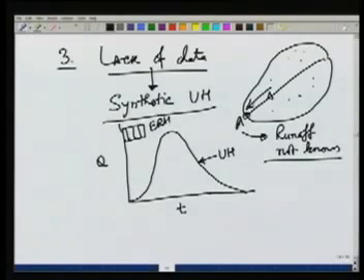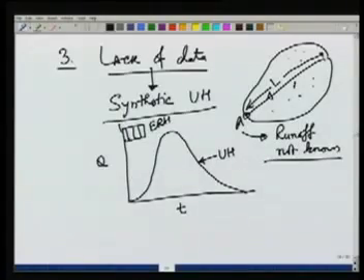So one of the important basin properties, for example, is the length. This will depend on the size of the basin. So larger the length, larger will be the size of the basin. Another important property which represents the shape of the basin is called LC, which is the length to the centroid, where this point is the centroid of the catchment area, and we take a point which is just opposite the centroid on the stream and find out LC along the stream up to the centroid point. This LC will characterize the shape of the catchment area.